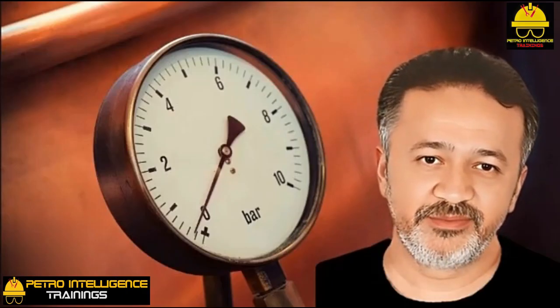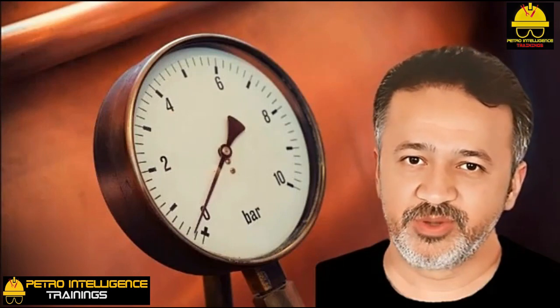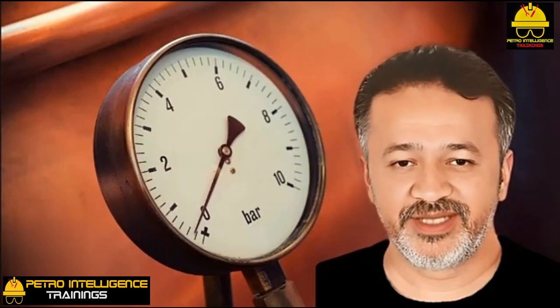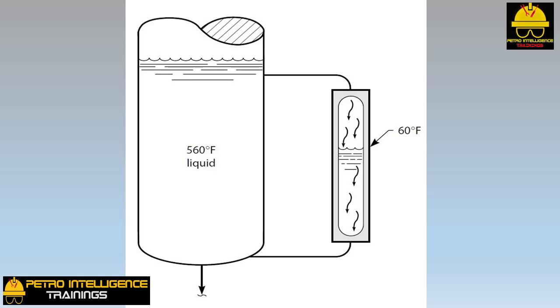High liquid level. In our calculation, we had 4 feet of liquid in the glass and 5 feet of liquid in the tower. But what happens if the distance between the two taps is 4 feet 6 inches? You can see a picture of the observed result. Liquid circulates through the glass, pouring through the top tap, and draining through the bottom tap. The apparent liquid level would then be somewhere between 4 feet 0 inches and 4 feet 6 inches, let's say 4 feet 2 inches. The indicated liquid level on the control room chart would then be 92%, that is, 4 feet 2 inches divided by 4 feet 6 inches.